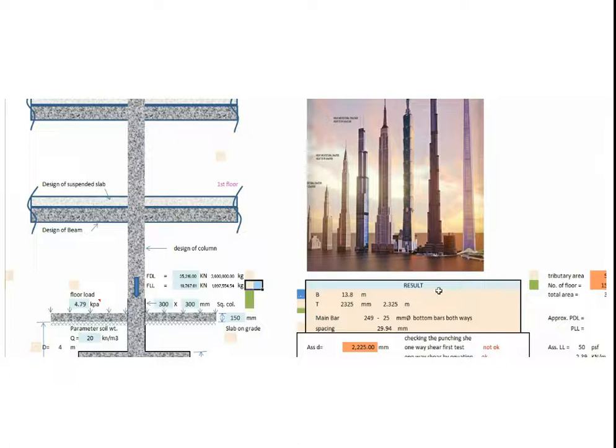Live load is load that can change over time, such as when people are walking around in a building. It is anything in a building that is not fixed to the structure. In this example we have live load of 10767.01 kN. See also the kilogram conversion for visualization. In this example we use number of floors 150, with tributary area of interior member of 5 meters by 5 meters.